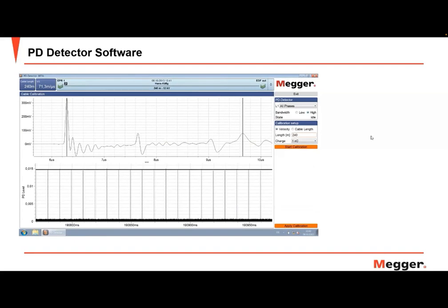So you can see that it provides a very good signal to noise ratio there. And there's actually a screen past this, we don't show it, but it's the disturbance level where you can quantify the background noise. If we look at the top, you can see the calibration itself where we have a very strong signal on the near end. You can see the very first splice there. A little bit after, you can see the second splice, and then just after the second splice, you can see the nice reflection from the far end of the cable.